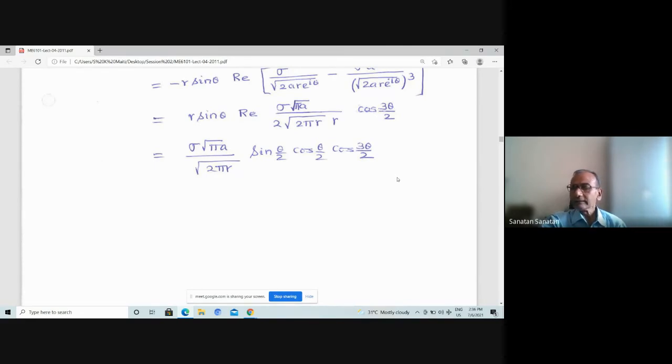So if you write that each point in space has displacement x and y, or u and v, in 2 dimensions, then you have to find out u as a function of xy, v as a function of xy, or you have to find sigma x stress as a function of x and y, and then sigma y as a function of xy, and tau xy as a function of x and y. This is a 2-dimensional problem. In the case of 3-dimensional problems, you have 6 stress functions: sigma x, sigma y, sigma z, tau xy, tau yz, tau xz. So these 6 stress functions are functions of 3 coordinates x, y, z.